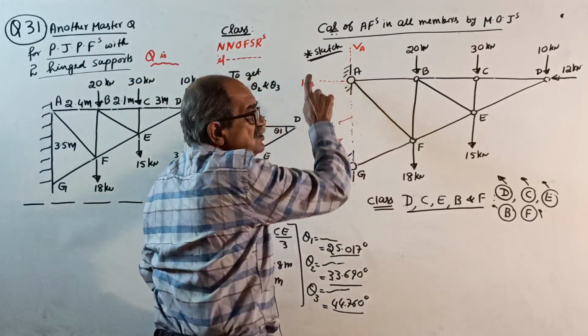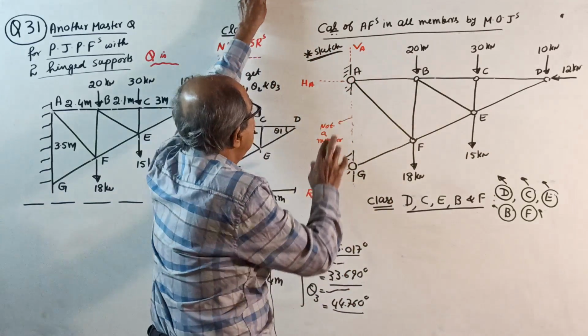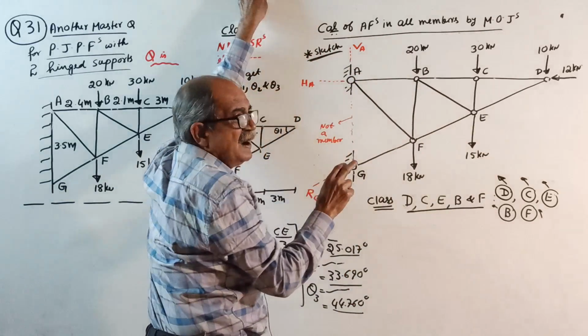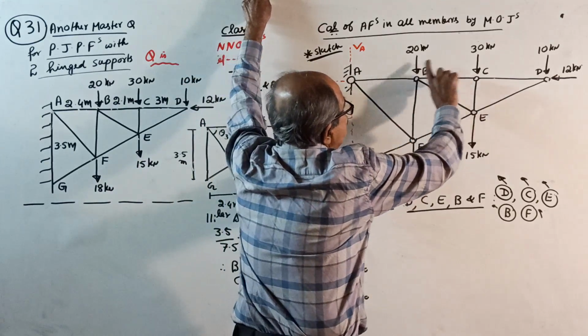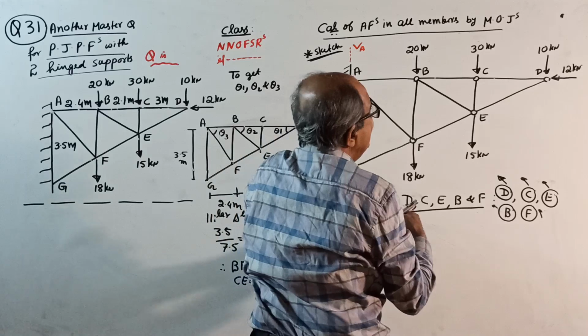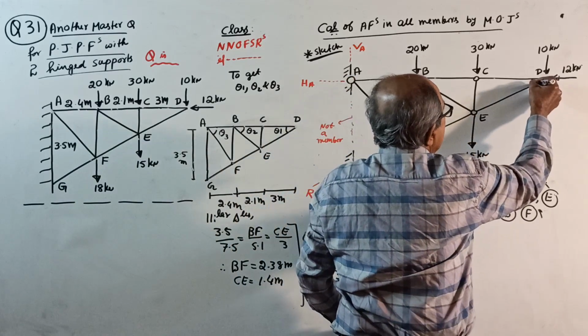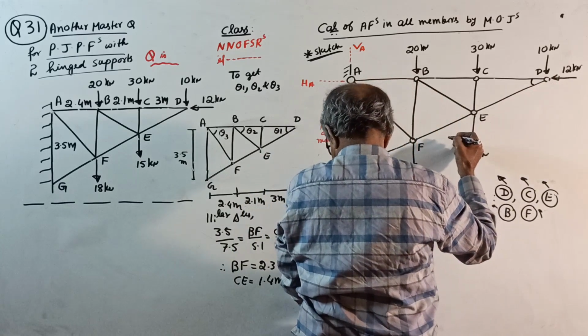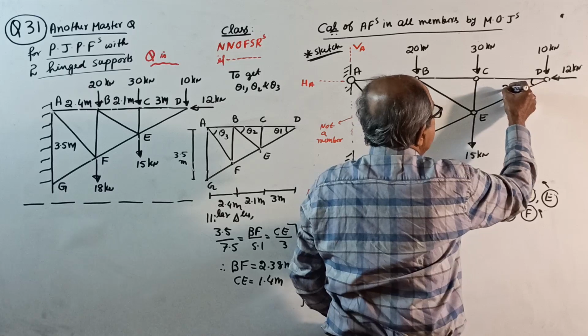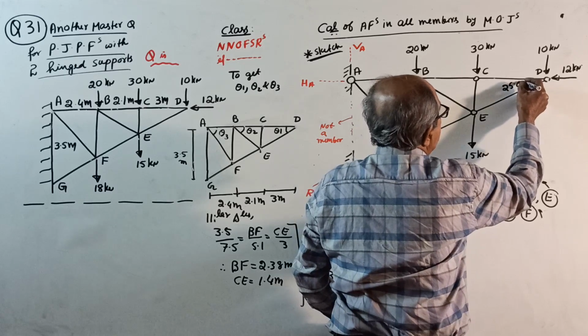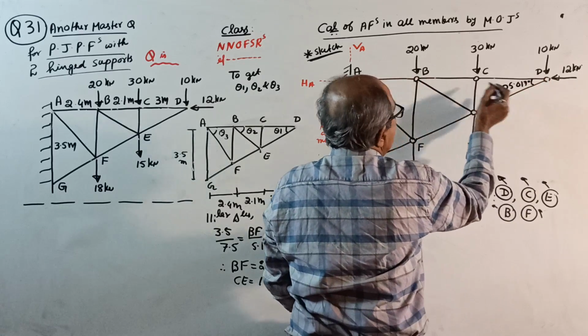Okay. Draw the neat sketch. I used to call it a star sketch. Then the reactions, I entered just for understanding; don't enter now. Everything is ready here. Mark the angle for all inclined members. See, this full line angle is how much? 25.017 degrees. Not 17.